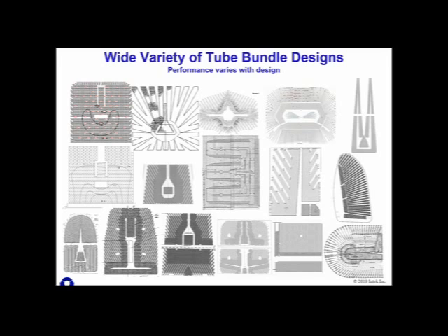In those designs, the ammonia in the condensate would etch away the Admiralty brass tubes in a region right at the support plates where the tube is passing through the support plate, because that's where the gap between the OD of the tube and the ID of the tube support plate hole is where water would get trapped, and not just condensate water, but also condensate with dissolved ammonia in it. That stagnated water right there would react with the copper in the Admiralty brass tubes and etch away the tubes. That's called ammonia grooving, where the tube wall is corroded and eroded away because of that chemical reaction.